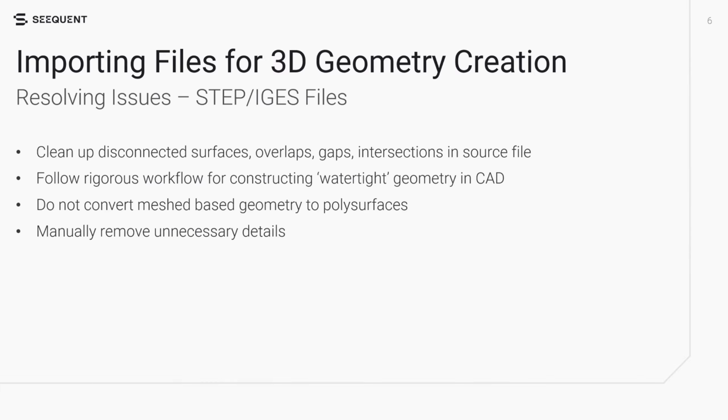GeoStudio's 3D geometries are natively parametric, meaning that they are made of NURBS solids, surfaces, and curves. This type of geometry can be created in GeoStudio 3D or imported from STEP or IGES files. Parametric geometry can be used in or created with all of GeoStudio's 3D tools, including cutting, merging, sweeping, etc. However, you cannot do this with mesh-based geometry, for example, those imported using a geological model volume from Leapfrog or